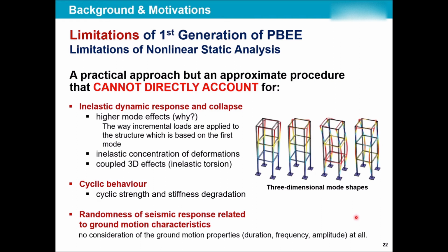Now, what about higher modes, where one bit of the structure, let's say the first floor and the second floor, goes forward, while the third floor and the fourth floor goes backward? Something similar to this case. You see, these two floors are coming forward while this floor is going backward. Some of them come toward each other, some of them go in the other direction. So the higher modes, let's call them, if this is T1, where the structure goes only to the right and all of the floors are going to the right, and this is T2, T3, and T4, what about T4 and T3?